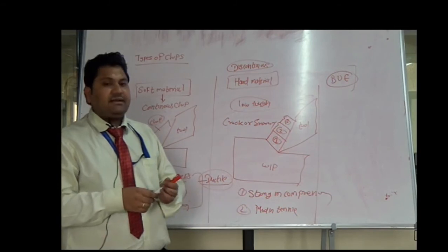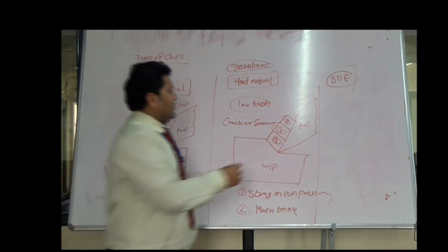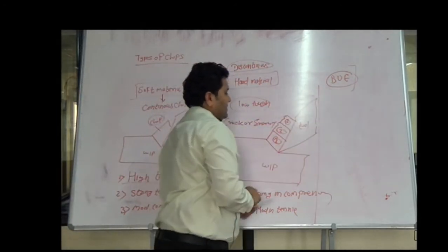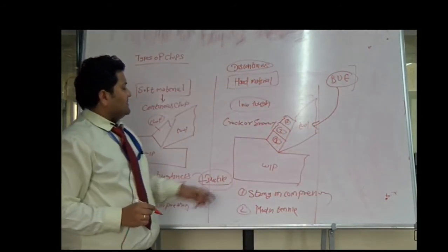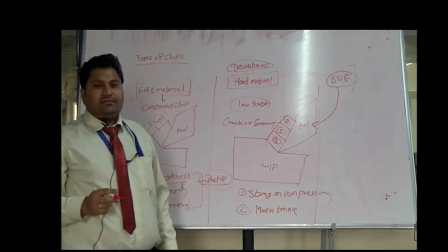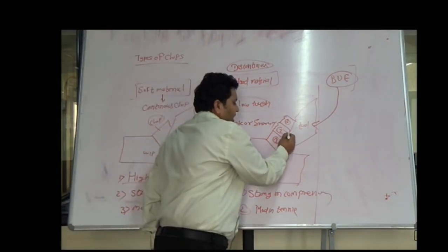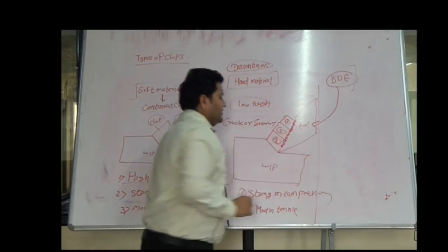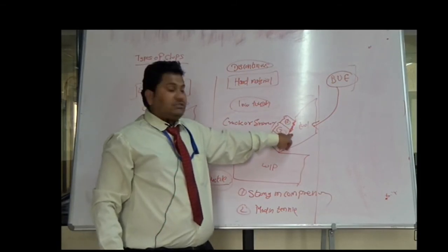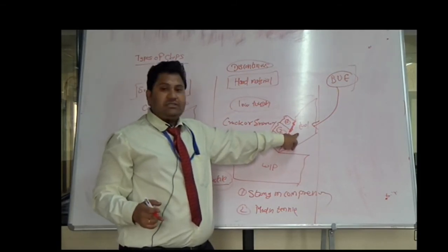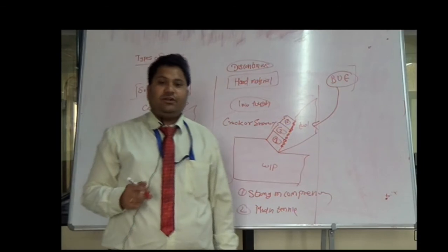So you have to elaborate in the diagram. You have to draw the diagram, again drawing the basic elements. This is a built up edge. Now you have to see this condition. During machining, the microchips are formed and exposed to the high-temperature machining environment. The maximum temperature is at these positions. Under some conditions, these microchips get welded or adhered to the tool, and a built up edge takes place.